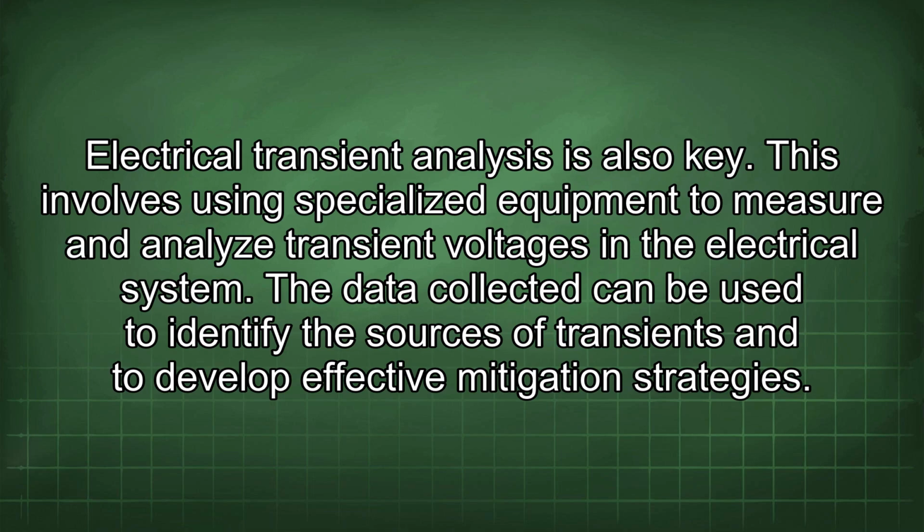Electrical transient analysis is also key. This involves using specialized equipment to measure and analyze transient voltages in the electrical system. The data collected can be used to identify the sources of transients and to develop effective mitigation strategies.